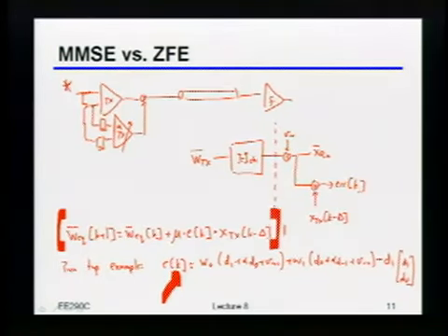But in DFE, you also do not have x of tx, right? Oh, okay. The only way I have an estimate of x of tx is by assuming that I received the correct data bit. So you're right, I don't technically have the transmitted data bit, unless, of course, I made the right decision, which we're going to have to assume in any case because the DFE was recursive to begin with. Does that make sense?